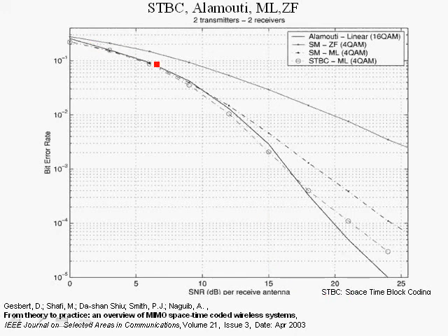And the family of curves over here, let's start out with the top curve. That corresponds to spatial multiplexing using zero forcing, and this is a 2x2 system. So in the case of the top curve, we're using the 2x2 MIMO system with zero forcing equalizer, which we have discussed, and we see its performance, the bit error rate versus the signal to noise ratio per receive antenna.